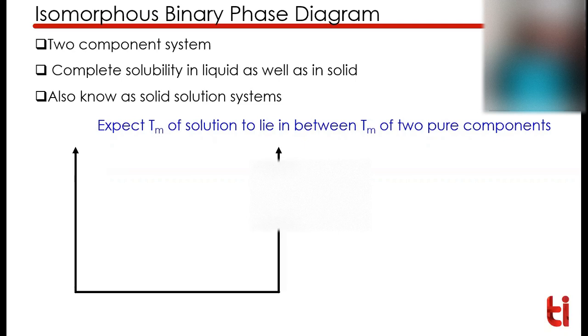So that's why I wrote, if I'm taking phase diagrams, the y-axis, when I'm talking about a binary phase diagram, pressure is constant, 1 atmosphere we consider. I mentioned Gibbs phase rule is F equal to C minus P plus 1.